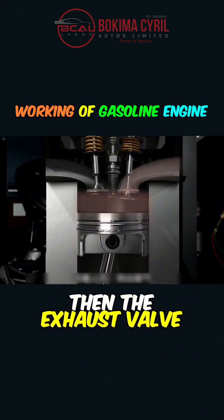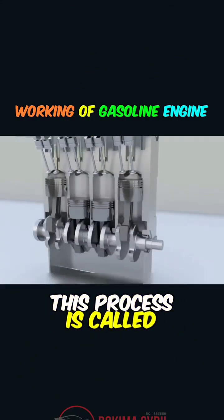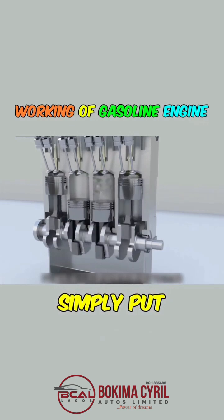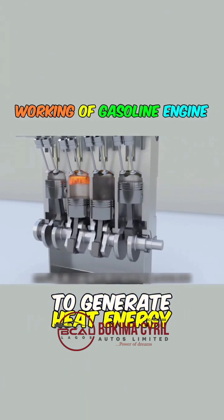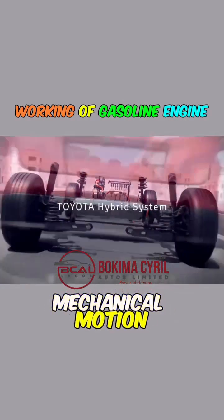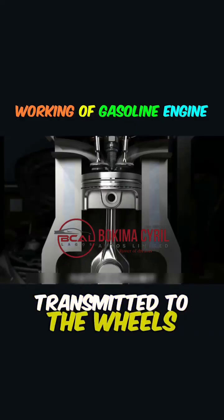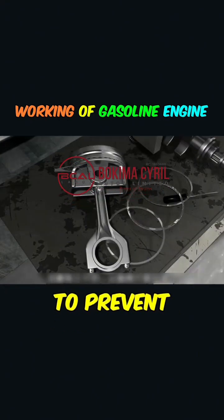Then the exhaust valve opens and the piston rises to expel the exhaust gas. This process is called the exhaust stroke. Simply put, gasoline burns in this internal structure to generate heat energy. The special design of the crankshaft converts this energy into mechanical motion, which is finally transmitted to the wheels as continuous power. Coolant circulates around the cylinder to prevent overheating.